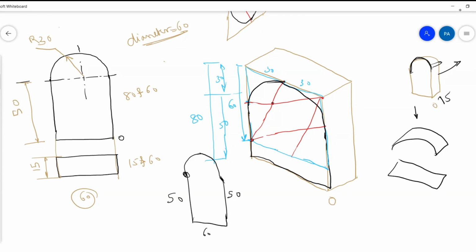Okay, so now pay attention. What I am doing is extending each and every point. In which direction? Towards this direction. So I can say to the right side of O. By what dimension? 15. See here, 15. Here, if it was 20 we took 20, if it was 10 we took 10. Now it is 15. So pay attention. 15 from O, and then the vertical dimension, how far will it come? This vertical line will also come. What will be the measure of this? This measure will be 50. So you don't have to measure. You just have to take the roller scale, draw a parallel line, and then draw a vertical line like this. That's it.